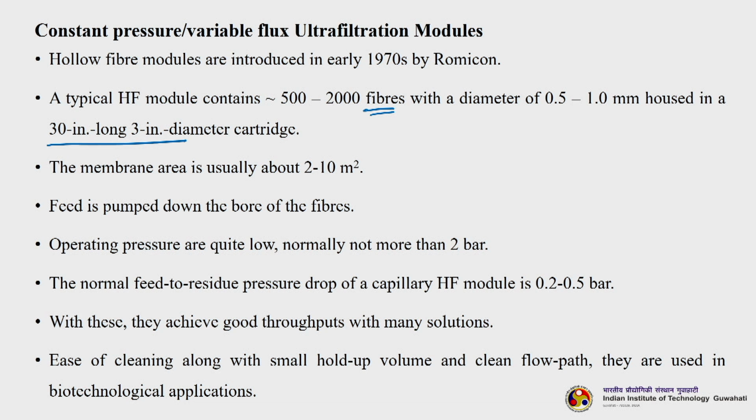Feed is pumped down the bore of the fibers and operating pressures are quite low, normally not more than 2 bar. The normal feed to residue pressure drop for a capillary hollow fiber module is 0.2 to 0.5 bar. With this they achieve good throughputs with many solutions, ease of cleaning along with small hold up volume and a clean flow path.